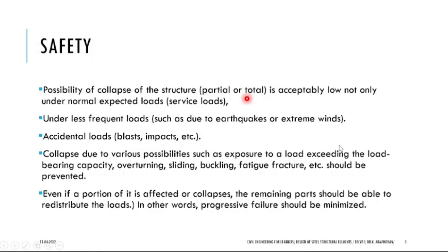60 years for what? Safety. And if your building is going to collapse, it should not collapse immediately. It should be a progress, or it should be a process. See, if a building is going to collapse, at the first level it has to attain cracks. Without a crack, a structural designer should not build a structure like that. It should not immediately collapse.